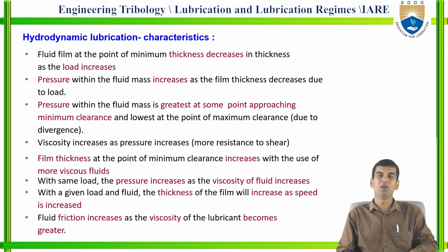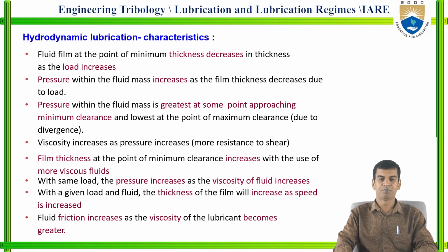With the same load, pressure increases as the viscosity of the fluid increases. The thickness of the film will increase as the speed is increased. The fluid film increases as the viscosity of the lubricant becomes greater.